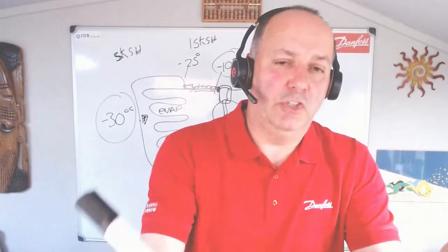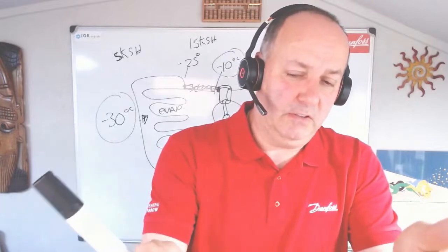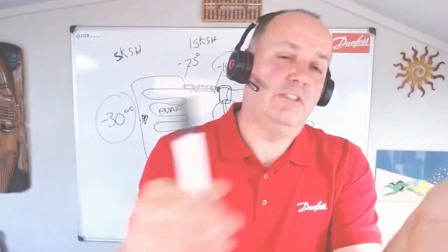Basically, the outcome was that actually, no, you're fine. But I think that depended on how much of the charge you'd lost. If it was less than half the charge, you were generally okay to top it up again. But if you'd lost greater than half, then really you should reclaim and fill up with a brand new charge. But that's an interesting question, I have to say.